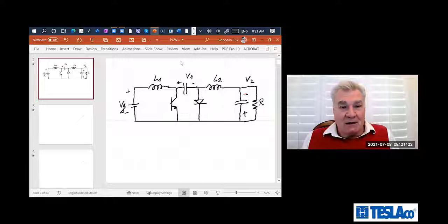And I emphasize that power electronics is all about power conversion and minimizing the number of components, devices, capacitors, switches, etc., and maximizing performance. Opposite of integrated circuits, where you put in as many transistors as you want. And then adding capacitors, like capacitive switching is popular, and adding inductors. And I showed you that one inductor is useless because it carries DC power and it is a DC current, and therefore, as we'll get to later, it is really useless as a component because it is extremely limiting in current, limiting in power, and limiting in size.